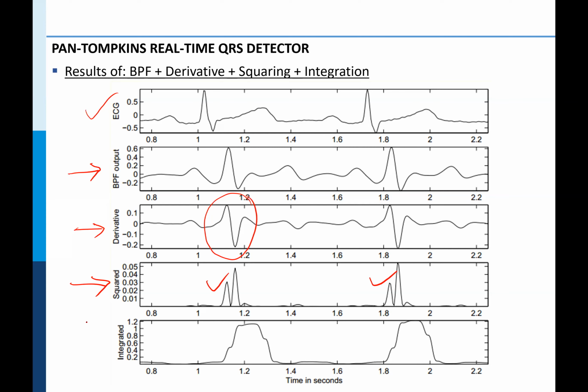Two pulses are shown, so there are two QRS complexes, or two R peaks. It also allows us to get the width of the QRS complex, just like we discussed before, because this width would give us a reliable and robust estimate of the QRS pulse width. That's the graphical illustration of the various things we have seen.